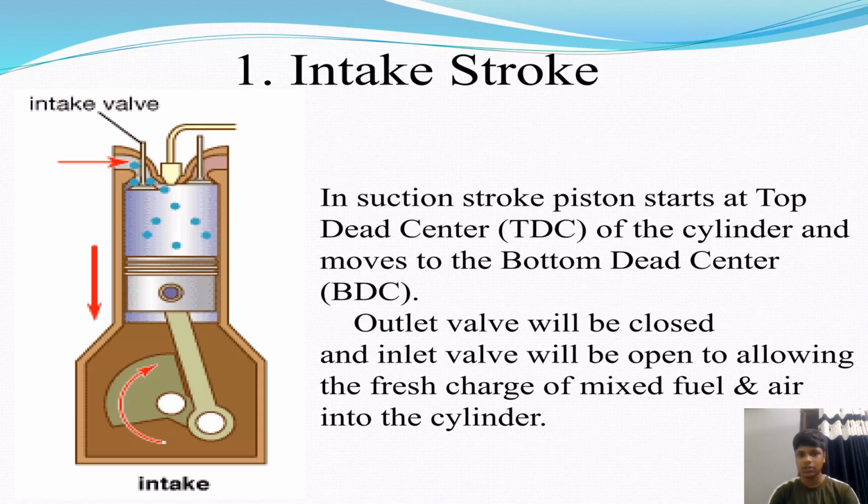First, intake stroke. It is also called as suction stroke. In suction stroke, piston starts at top dead center, which we call TDC, of the cylinder, and moves to the bottom dead center, BDC. Outlet valve will be closed and inlet valve will be open to allow the fresh charge of mixture of fuel and air into the cylinder.